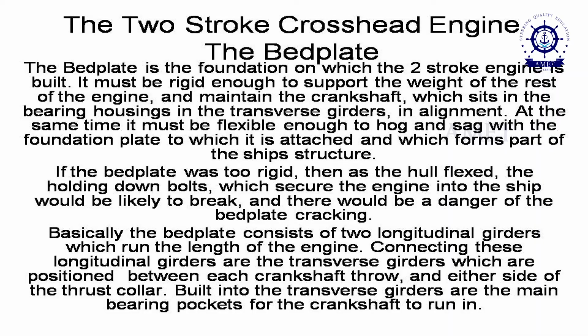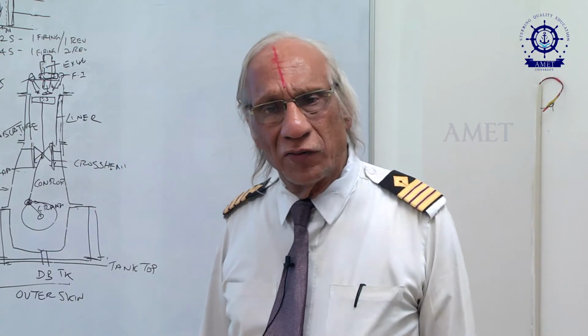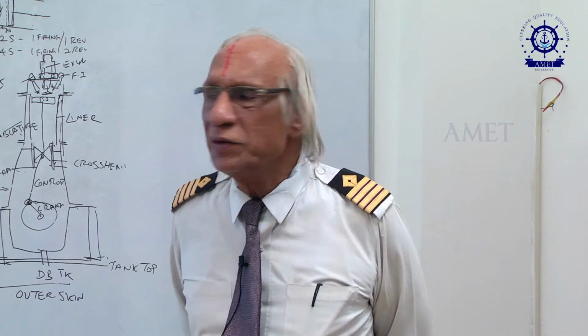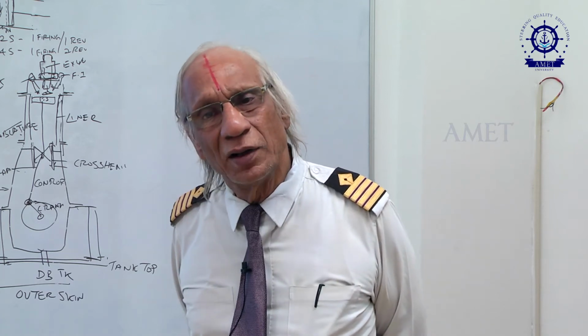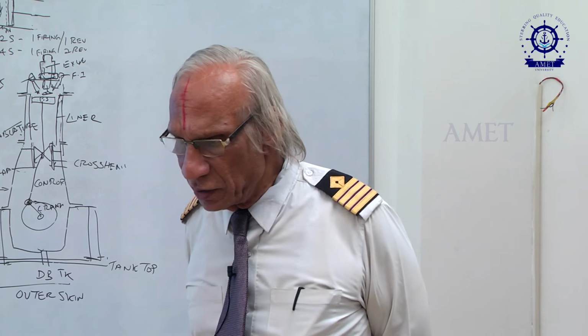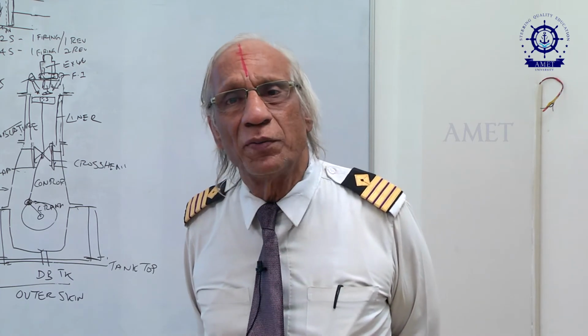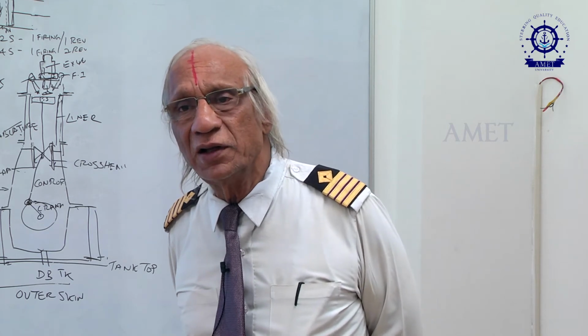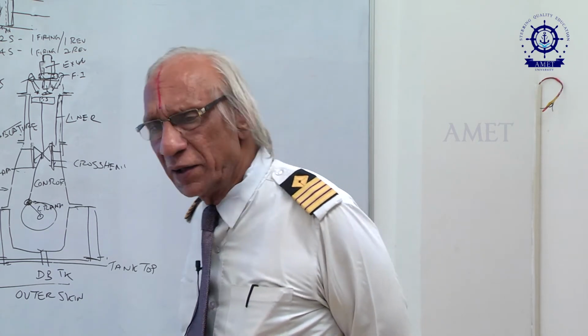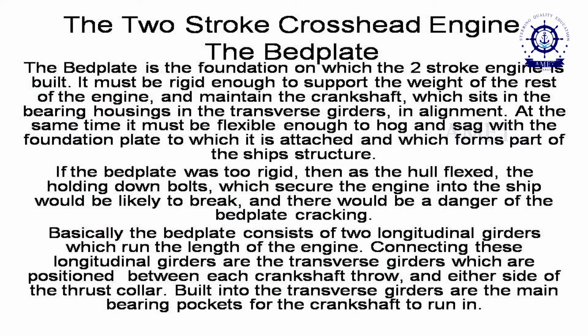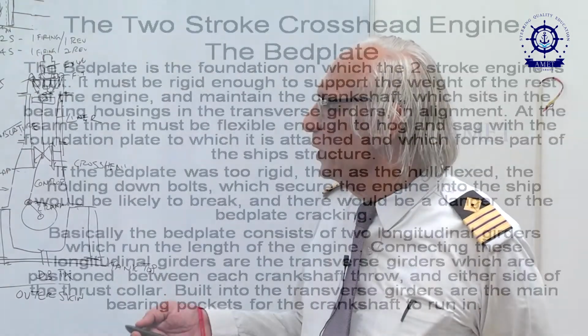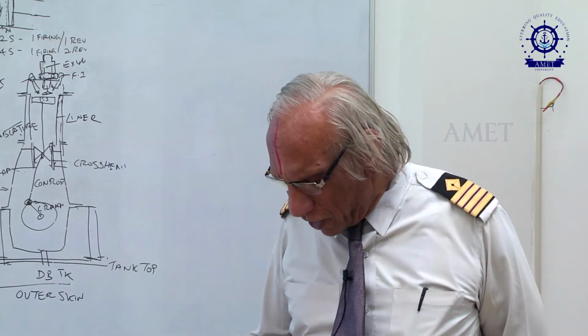The bed plate is nothing but a foundation. Every equipment requires a foundation. So here in the case of a diesel engine, it is the bed plate that is the foundation for the engine. The bed plate is supported by its position onto the tank top or the double bottom tank, the inner skin of the ship. Bed plates, modern ones, are made of cast steel. As you can see here, what is the requirement of the bed plate?